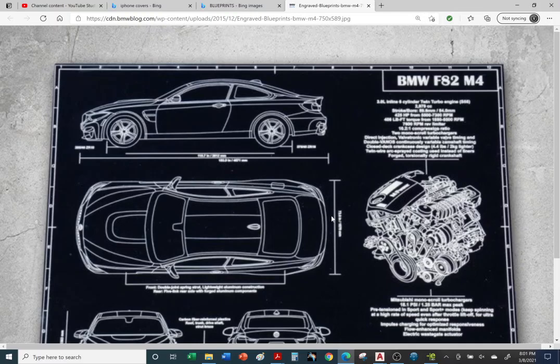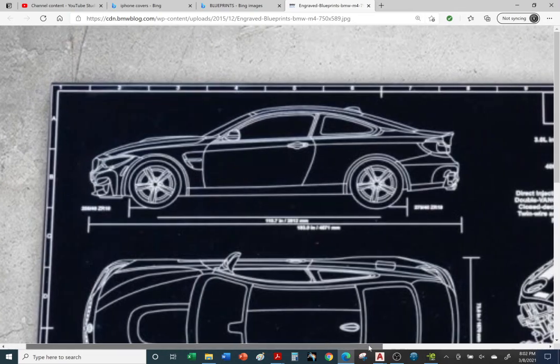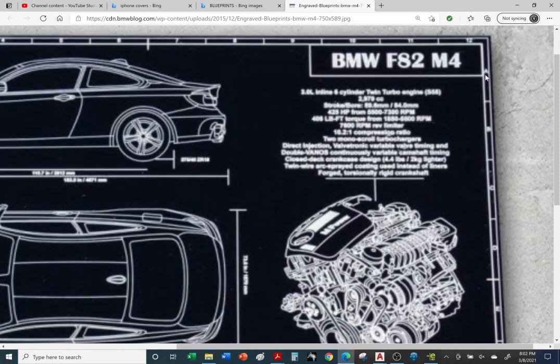So let's say we were going to change this dimension. Up in the upper right corner, under our new revision, we're going to say we changed this dimension. But which dimension? There's a bunch of dimensions. Notice this is A. I know it's hard to see, but this is the letter A, B, C, D, and so on, and this is 4, 5, 6, 7, 8. So you're going to say, look at zone D, 8.